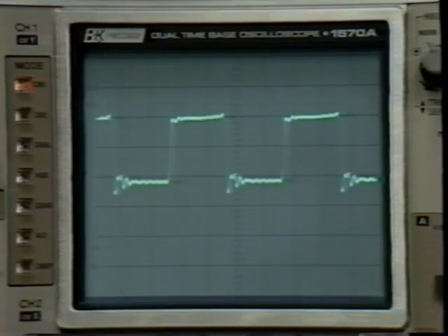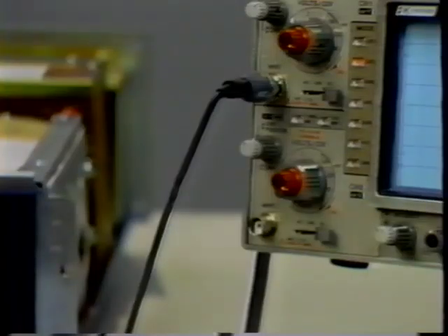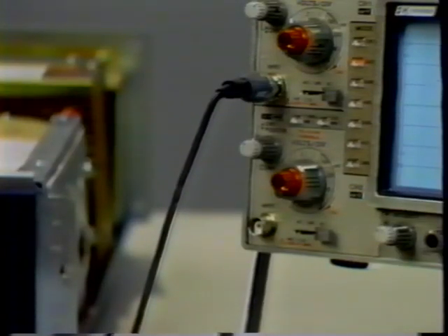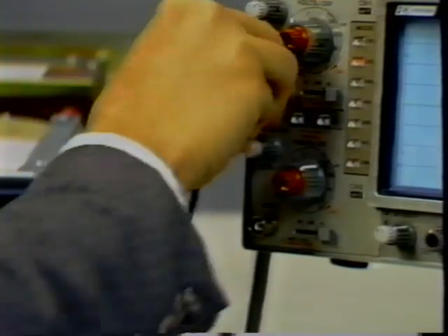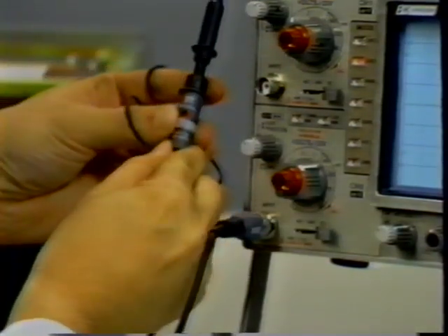Another problem that a misaligned probe may cause is ringing, caused by unwanted resonance in the scope's input circuit. This is what ringing may look like. To prevent this type of inaccuracy, check your probes before each use. It is especially important to realign probes when they are moved from one channel or from one scope to another.